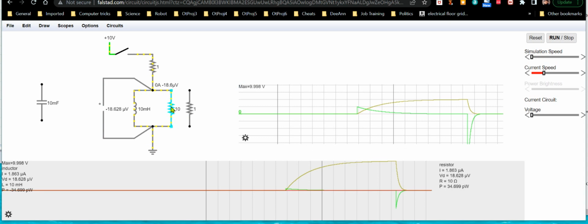and plus, by the way, if I had used a tenth of an ohm resistor, a 0.1 ohm resistor, it would have taken 10 times longer to discharge, and instead of 10 volts across it, it only would have generated 1 volt across it. So it would take like 10 times longer to discharge. So it works the opposite way too. But it's more interesting if you're interested in high voltages. This is a way of generating high voltage. But it's going to be much briefer than how you charged it.